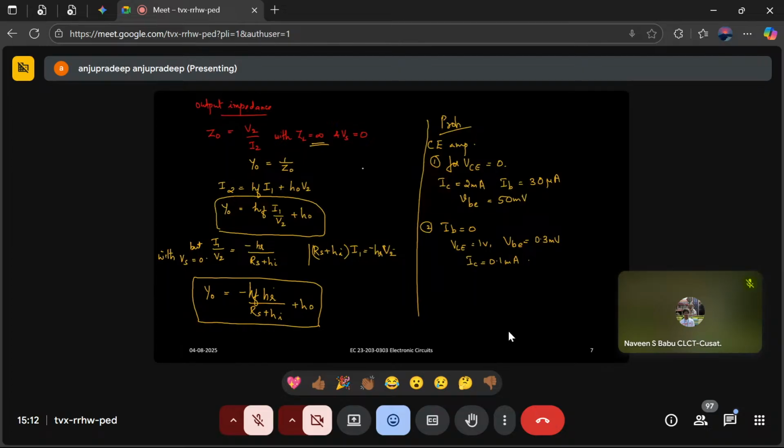Okay. So what I was saying is, when you want to measure one impedance, what you do is you give voltage at that port and measure what is the current flowing into the circuit. Voltage by current will give impedance. At the input side, it is not confusing because you know that only if you give some input, output will be produced. So you are giving voltage there, current is there. Now, when you come to output impedance, there also we don't call it as output, or we are not bothered about that.